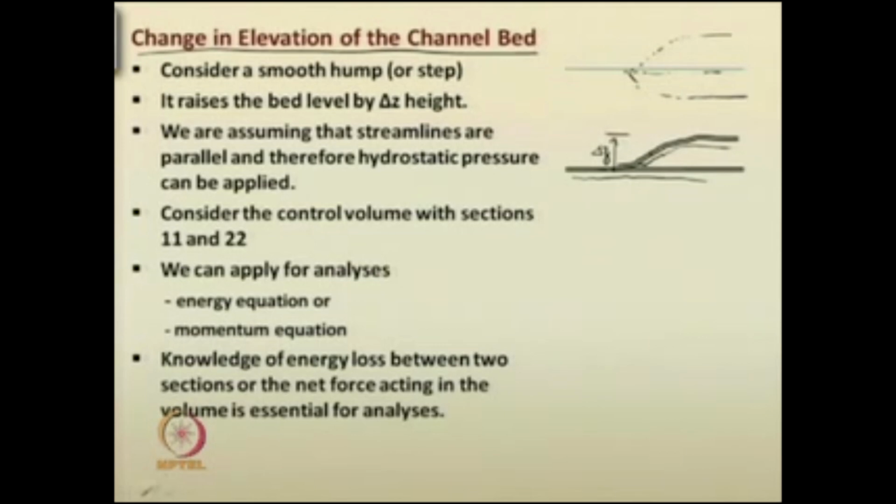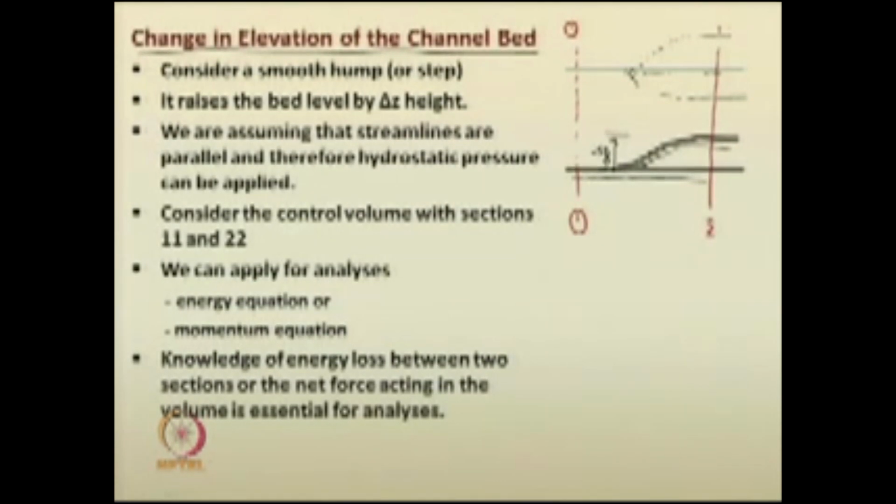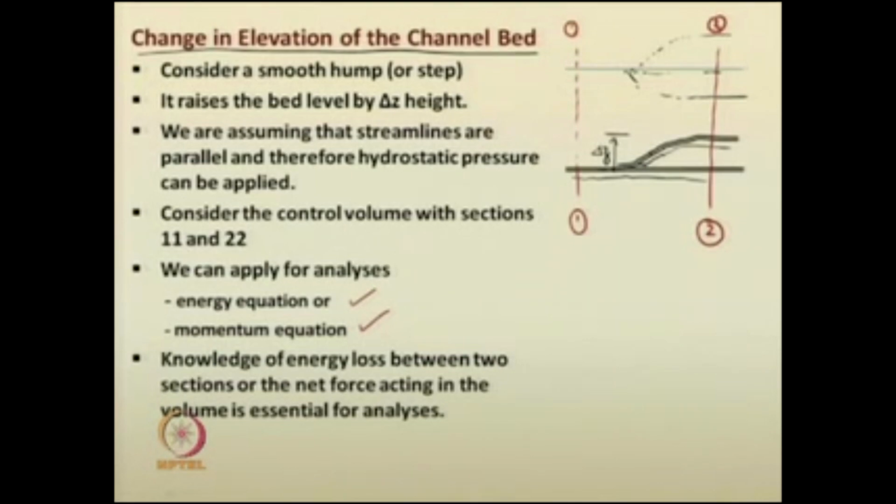So, let us consider two sections here as the bed is elevated. This is section 1 and let this be section 2. So, we are considering two sections in this particular rectangular channel flow, where the bed is elevated by a height delta z. We can use the energy equation for analysis, or the momentum equation. That is, you can compare the energies at the two sections, or you can use the momentum equation for the entire control volume enclosed in these sections.